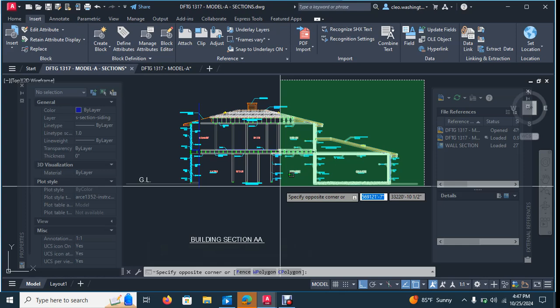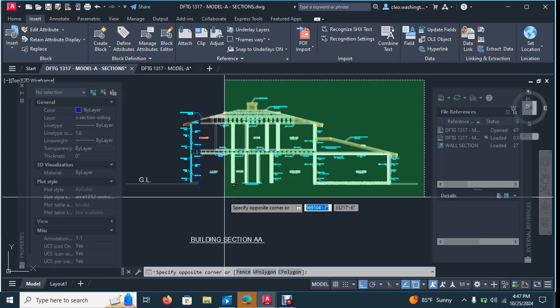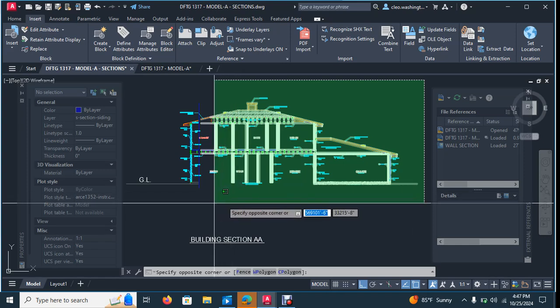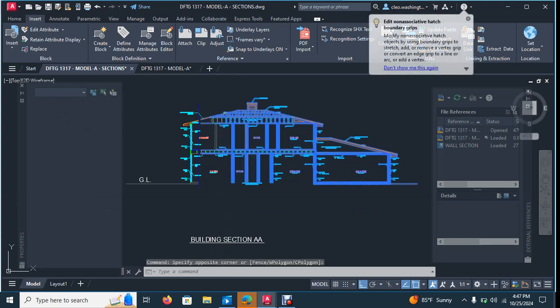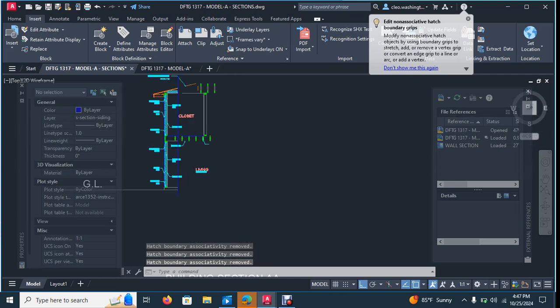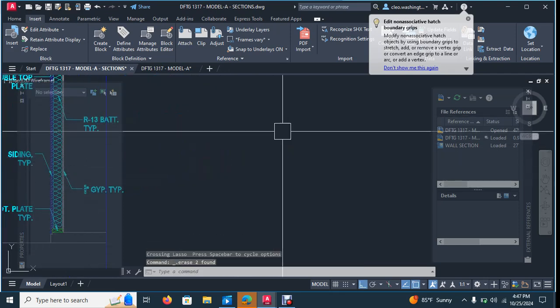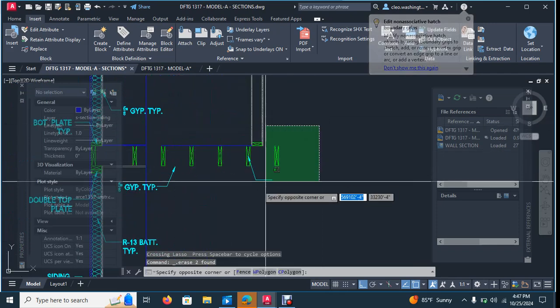And I just want to let you know that once I do roll those videos out, once we start creating sheets and once we actually start putting drawings on sheets and printing drawings, I want to make sure that we're all on the same page, okay? I saw some people that would actually put in the text or the dimensions in the sheet file. That is a big no-no. You can do it, however, it is not indicative of industry standard, okay? So keep your head on a swivel for that one, all right?